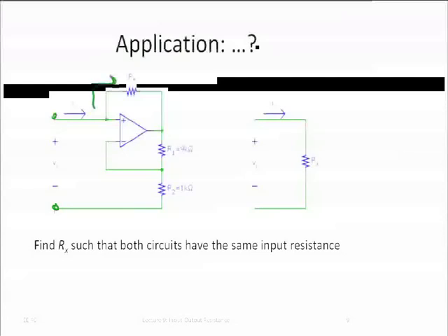Likewise, the operational amplifier's output can provide a lot of current. It's like a voltage source at its output. It defines what voltage there is at the output: it's V plus minus V minus, times the gain. That's the voltage there. It doesn't matter how much current it has to supply. So in particular, it does not matter how much current flows into RF, so it really doesn't matter what the value of RF is. RF equal to infinite would be just as good as any other value. The voltage V out is going to be the same regardless of whether RF is 1 kilohm, 100 kilohm, a megohm, or infinite.